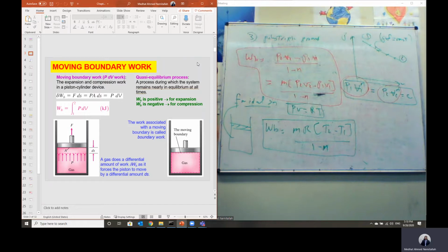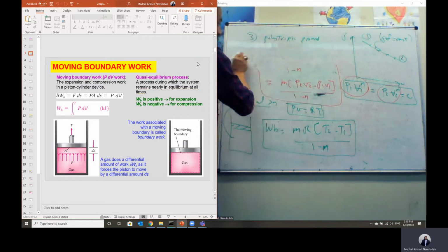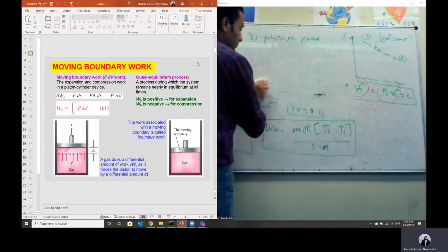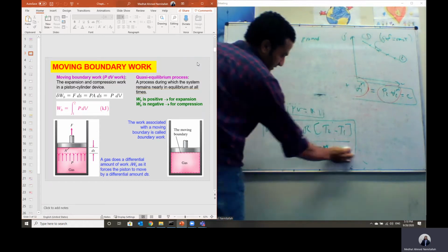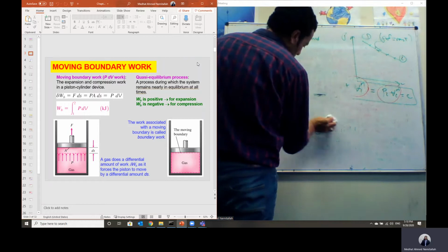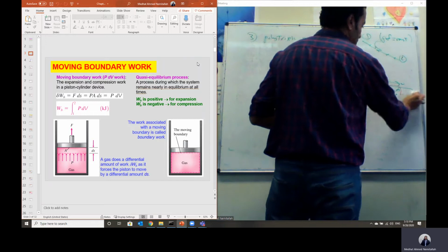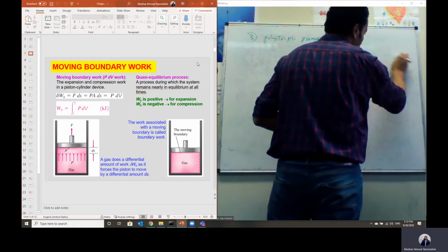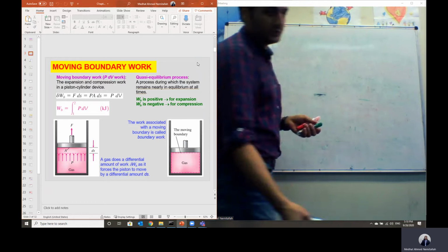So this will tell you for any application about the pressure relation, pressure with volume, when we have any working fluid in a piston cylinder device with the movement of the piston, then we have boundary work, and we have to calculate this boundary work through the integration of PdV. Okay. We are considering here some special cases. We have considered isochoric, the boundary work is 0. We have considered the case of isobaric, pressure is constant, then we calculate the boundary work through the integration of PdV. And when we have a polytropic process, then in this case also we can calculate boundary work through integration.